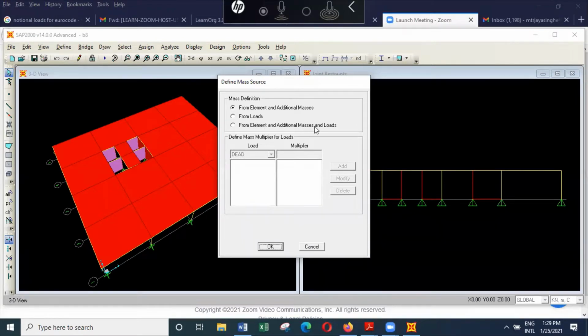And if you are going to place any additional masses, those also can be considered. But you can see the weight of the finishers. We have not modeled finishers in the building. In our model, there's nothing called finishers. Finishers is only a load. So we have to now convert this load that we consider as finishers to the actual structure. So what we do is